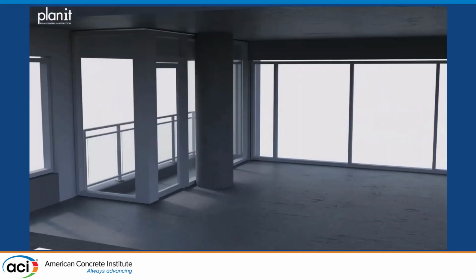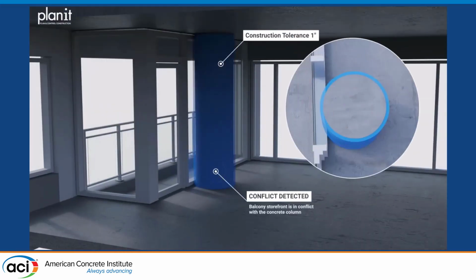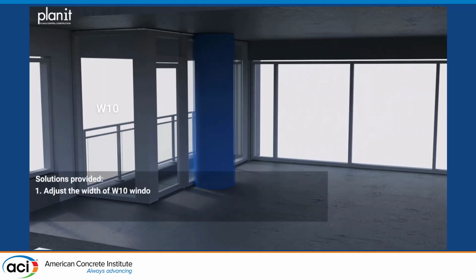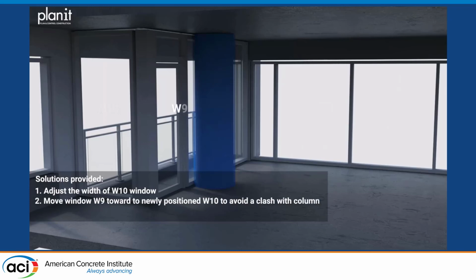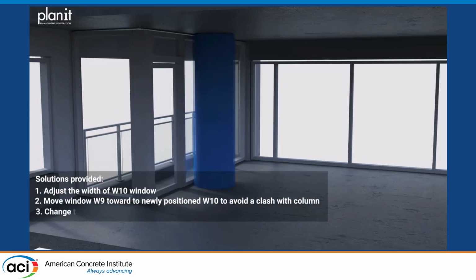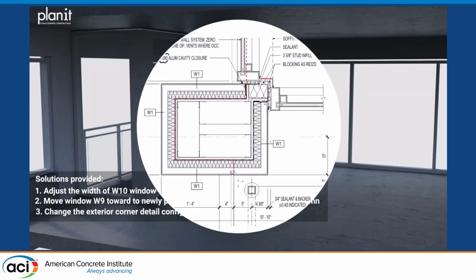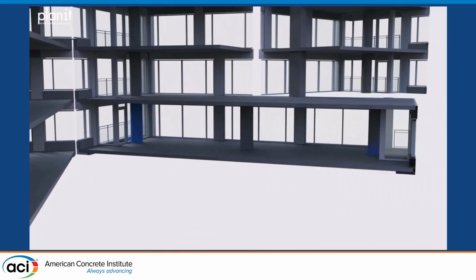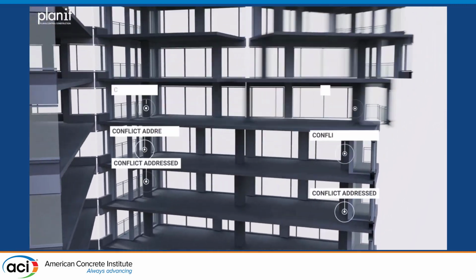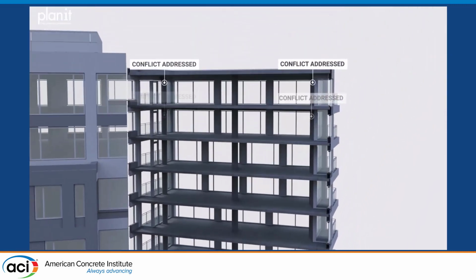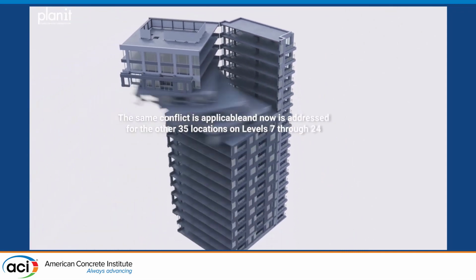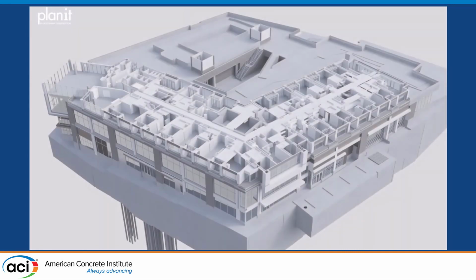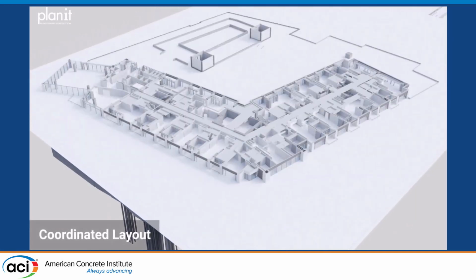Here's a good example of construction tolerances for exteriors. It happens on almost every project. When we actually apply the construction tolerances at the edge of slab, we often see conflict with vertical elements and the actual enclosure. That creates issues with fire safing at the edge of slab, oftentimes just accessibility and constructability in the field. Once we resolve those, there's 150 of those locations throughout the entire project. Sometimes we miss one, and then we're surprised how expensive that is, and the amount of fixes tells us what actually the amount of cost is that we have.